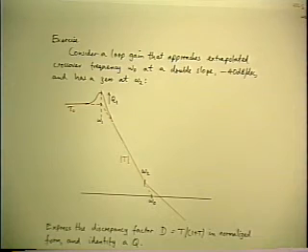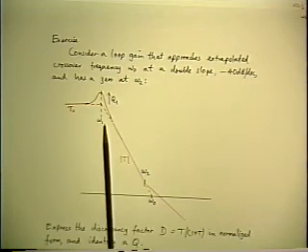And if you close a feedback loop around that switching converter in order to make a switching regulator out of it, then the loop gain is proportional to the transfer function of that LC filter. In other words, the LC filter characteristic shows up as part of the loop gain.